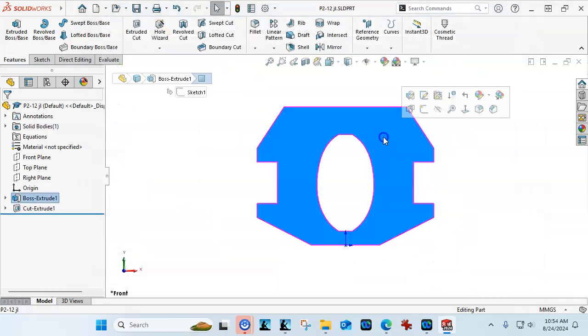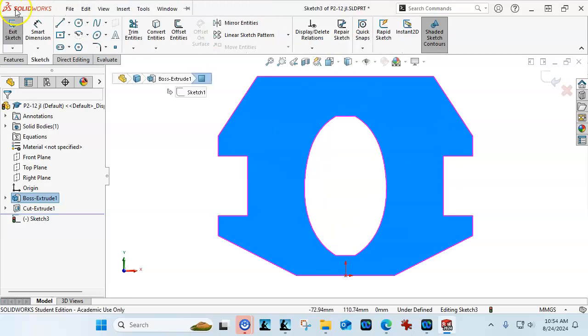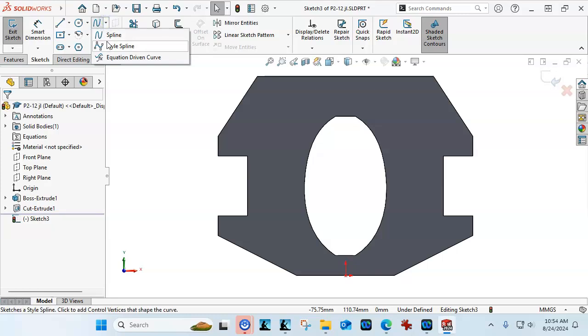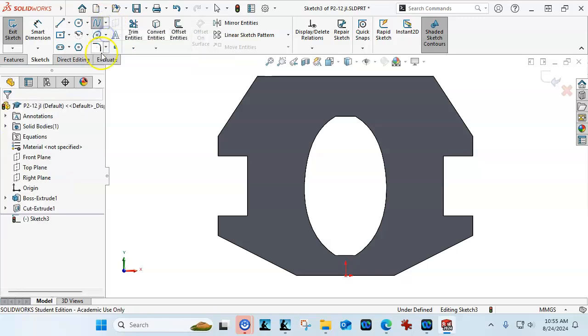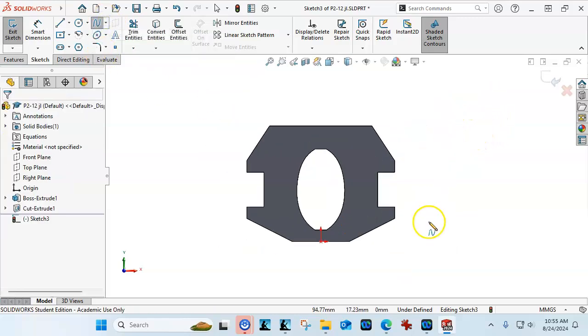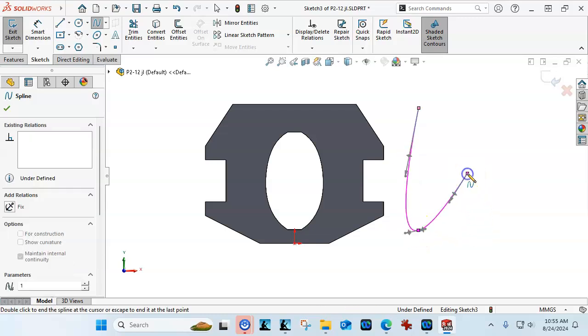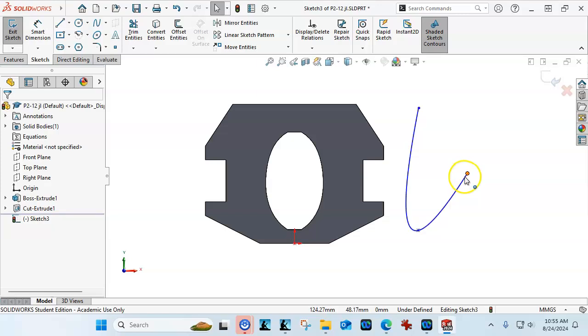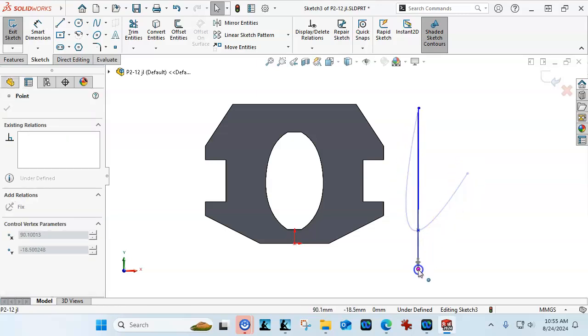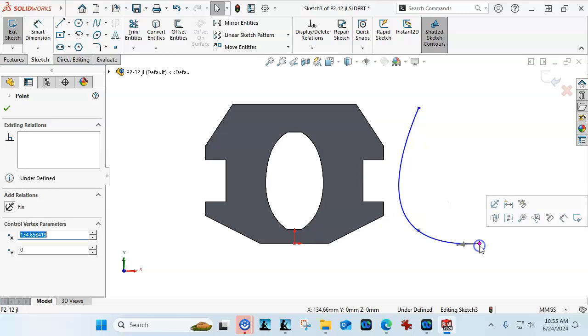All right, so now optionally, let's take a look at if you want to tinker with the splines. So if you had an art project, you're going to 3D print something that's on the wavy side. Let's go with the regular spline first. Let's just take a look at the simplest spline, 2 points. And it's not really showing me vertical. Oh, actually 3 points. So as I drag those around, we're going to see them kind of invert on themselves, be able to loop.